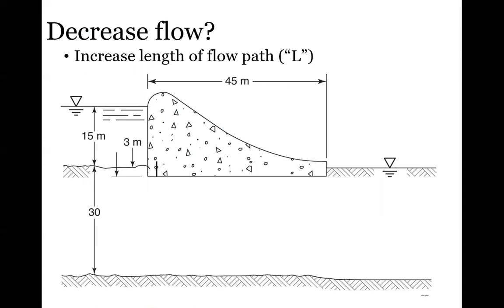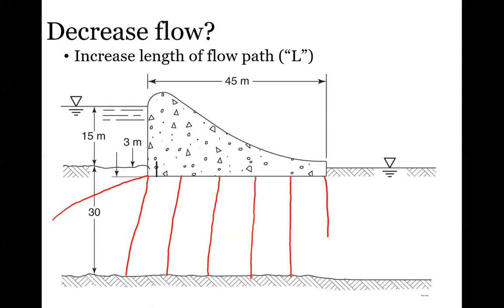You usually start with trying to discretize them this way, trying to get them as parallel as possible. But you can see that once we start drawing these flow lines, it gets a little tricky because we need them to always be square shape and we need them to intersect perpendicular to each other. In this case, this isn't even a square, but it's difficult to get it exactly. So for the second flow line, we would need to keep it square-like.